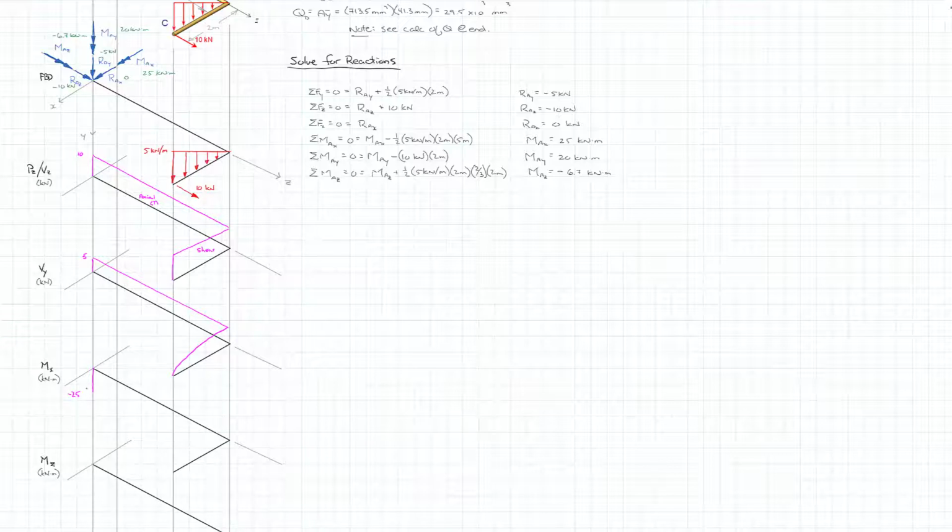Again, we're going to have to use a little bit of interpretation as we go through. And so that's going to vary linearly because the moment arm is decreasing until it gets to a value of 0 when we get to point B. And so I'm going to draw that in as a linear line as it gets to 0 out here. And then it doesn't continue between B and C. It just stays at a value of 0. So we're pretty happy with that.